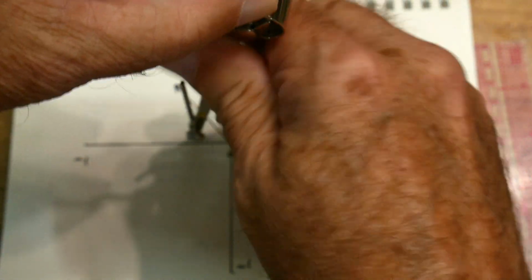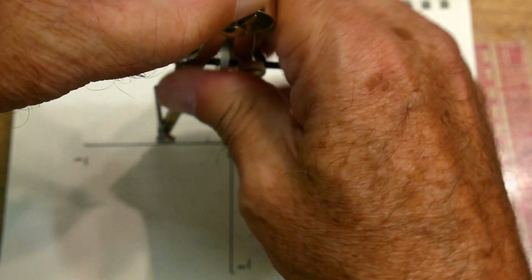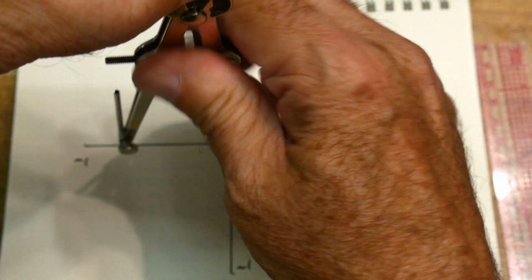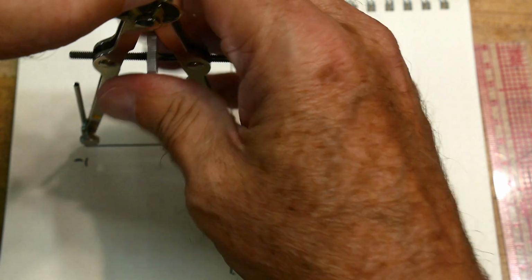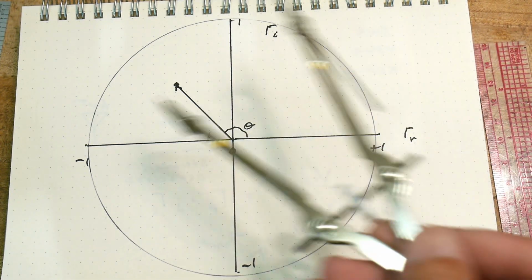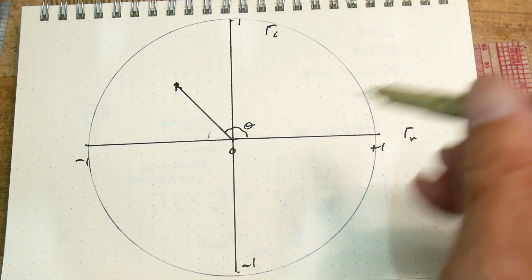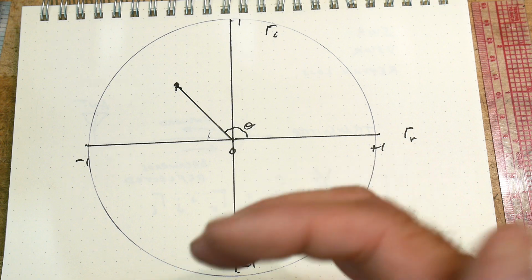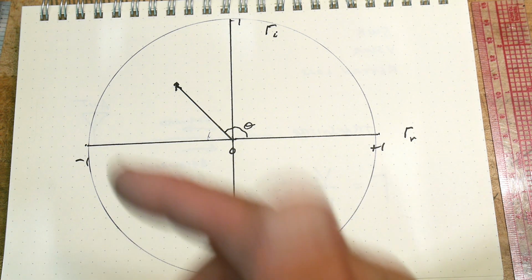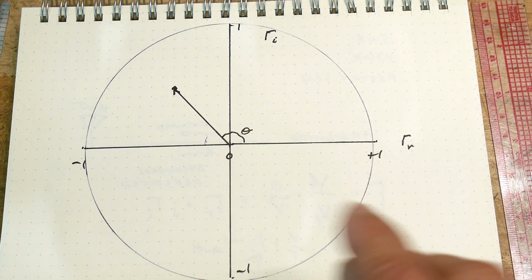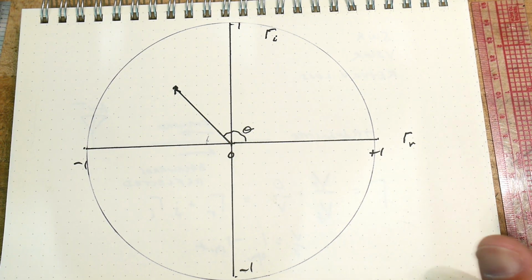And if we think about this, the idea that gamma can never be bigger than 1 actually means that is the maximum area in our graphing, right? We can't graph outside that because the absolute value of gamma, the vector length, can never be greater than 1. So we're always going to plot in a circle, okay? So that's just an interesting fact.